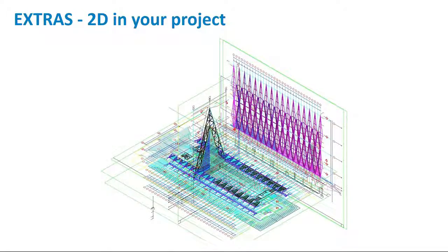But I really wanted to work from here, being able to actually use the DWGs in the Revit environment. I had a workflow where I linked the DWGs into a blank Revit model, and then that became a standalone Revit model. What happens with the DWGs, and I mentioned earlier that we were using Revit Server, is that the DWGs stay in the file, even though they're a link.